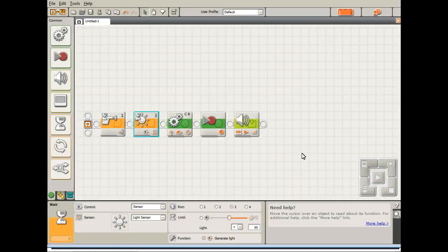But just about all these sensors where the sensing element is analog give you the ability to set that threshold, which we refer to as a sensitivity. So right here, this is where I set the sensitivity. This is where I say, okay, I'm either looking for light or I'm looking for dark. Right now it's set up to look for light, and this is where we set our sensitivity. You can set it by the slide, or you can come in here and set it numerically.